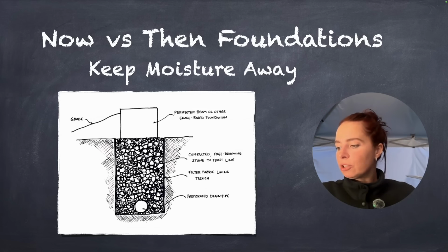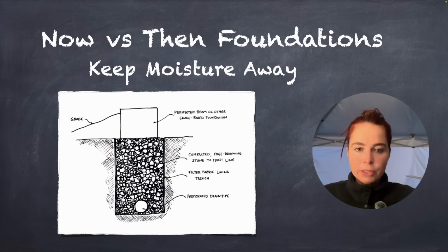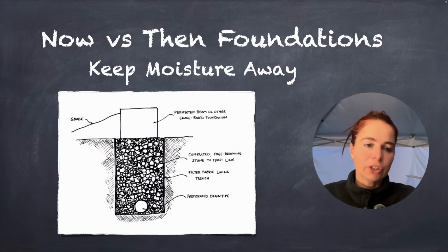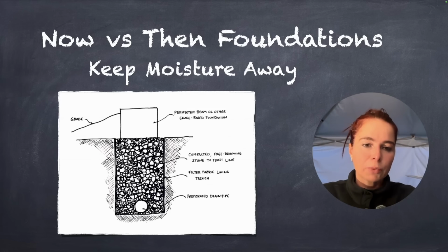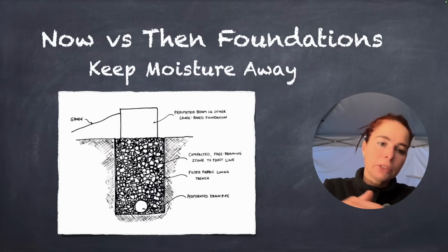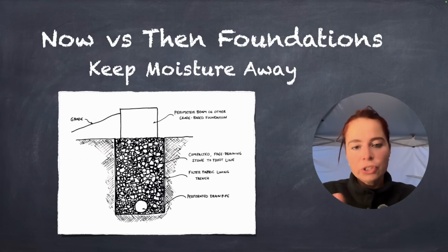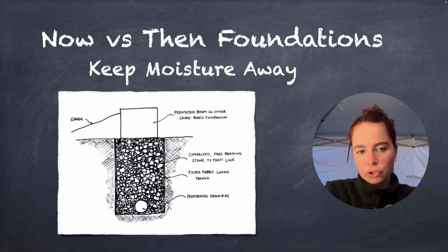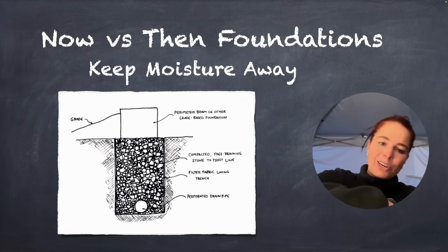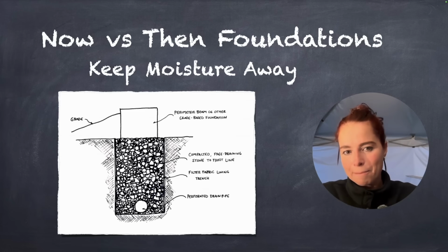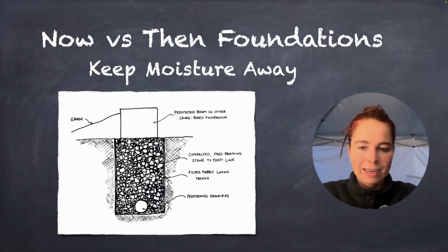And another thing I'm going to mention, in terms of moisture management, because it's an important principle, is you can see in this illustration that backfill. You see where it says grade on the left of the illustration there? That is backfill that is sloping away from the building, away from the foundation wall. Or I guess that's the perimeter grade beam, not the foundation. So you can see it sloping away, which encourages moisture to move away. You want to not have ground sloping towards a building, you want it sloping away. Super simple concept, but you'll be surprised at how often that idea is missed.